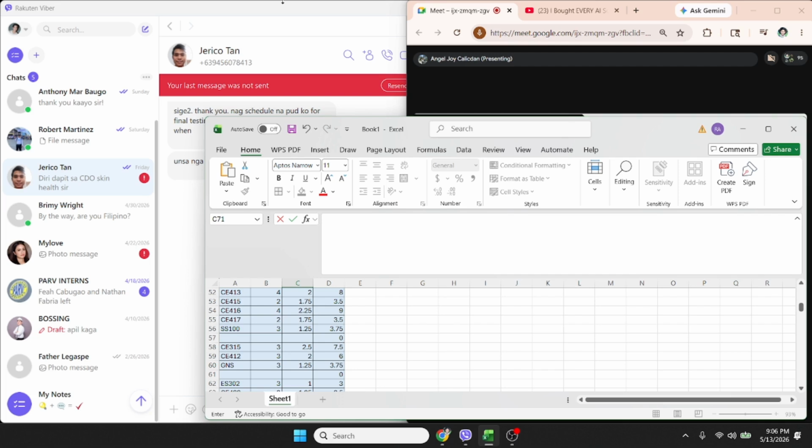So, this is 0.17 times 1 plus Nu over 14 Ag times lambda square root of fc' bw d. So, substitute all: Nu is 1,250 times 10 raised to 3 to convert to Newton, over 14